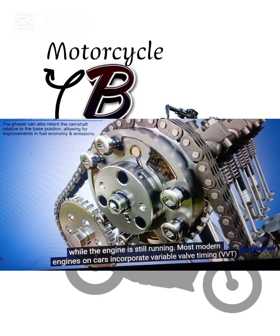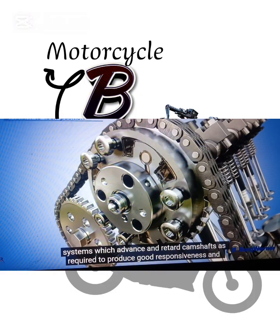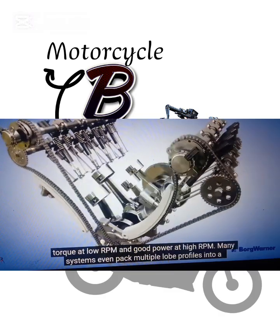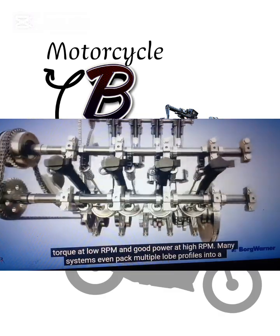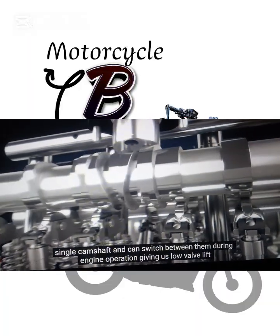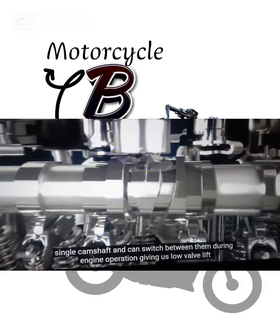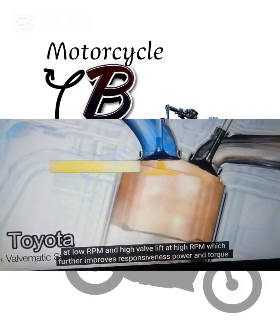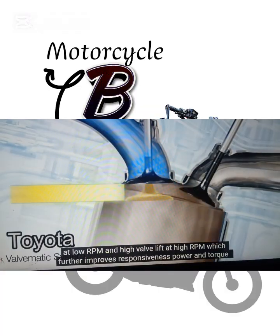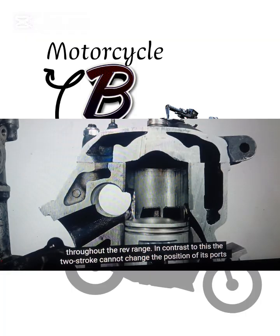Most modern engines on cars incorporate variable valve timing systems which advance and retard camshafts as required to produce good responsiveness and torque at low RPM and good power at high RPM. Many systems even pack multiple lobe profiles into a single camshaft and can switch between them during engine operation, giving us a low valve lift at low RPM and high valve lift at high RPM, which further improves responsiveness, power, and torque throughout the rev range. In contrast to this, the two-stroke cannot change the position of its ports.